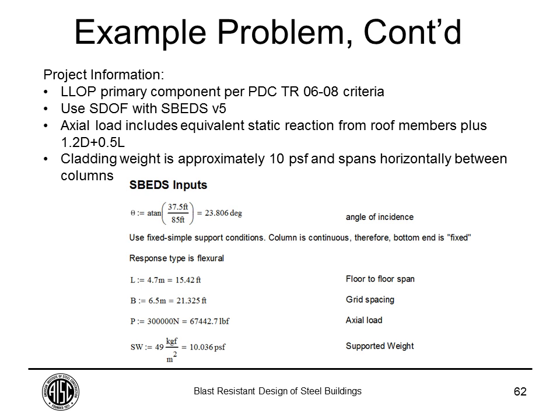Okay, thank you. And I think we have time for one more question. Do you include an increase in the modulus of elasticity due to a high strain rate? And the second part is, if we increase the average strength compared to the yield, won't this be unconservative if the material is at the limit of the yield stress, for example, 50 KSI?